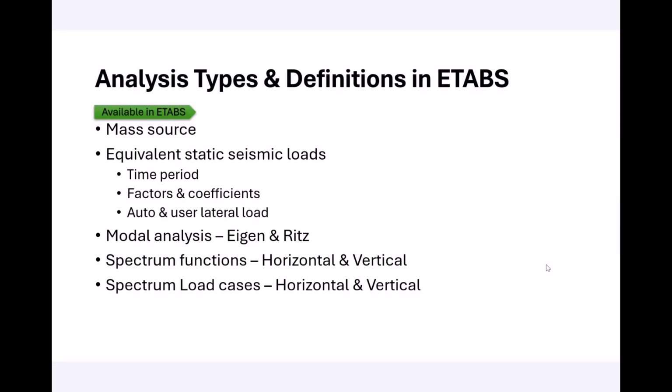Yeah. On the analysis types, so these are the major definitions that we are going to deal with in the program to input. The first one is the mass source, and then from the mass source, you will be defining the equivalent static, and in that we will be specifying the time period. So time period can be a user input using the empirical formula given in the code.